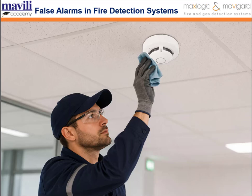And then we have the lack of periodic maintenance. For fire detection systems to function correctly and reliably, regular maintenance and testing procedures must be carried out without fail. Over time, dust accumulation in detectors, aging of electronic components such as photodiodes, transmitters, and receivers, loosening of connection points, and changes in environmental conditions can negatively affect the system performance also.